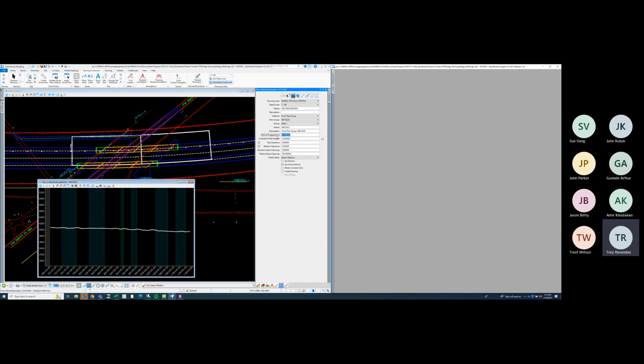So we're gonna want that at 1. And I guess the rest is fine to keep how it is. We'll click on this and use terrains, and then we'll follow the prompt here. So it's going to say identify profile view. So we'll left click in here.